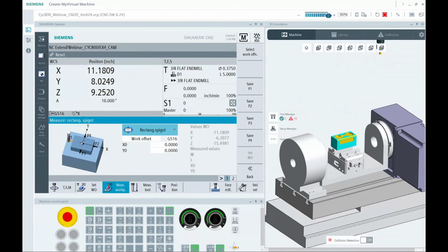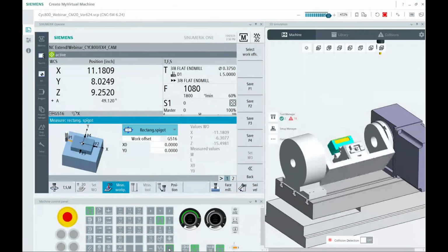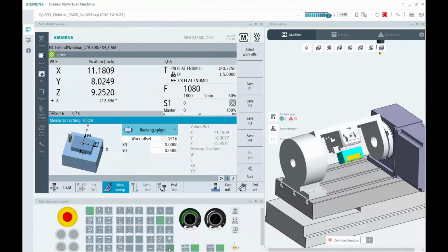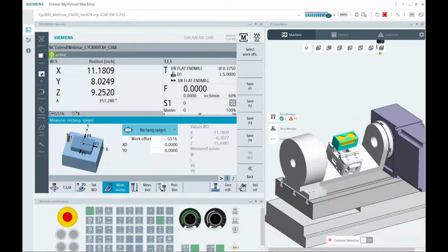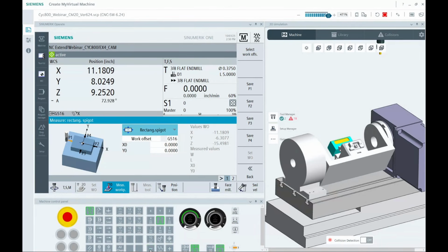The rotary axis is what we would refer to as a modulo axis. So if I was to jog this rotary, slow it down a little bit, I'll speed up a little more than that. So see how it just spins indefinitely? Now in this case, my part stack wouldn't hit the table. I'd be fine. But I could have an issue there. And I'm probably not going to want to start recommissioning this machine, so this overlap of this modulo functionality can't